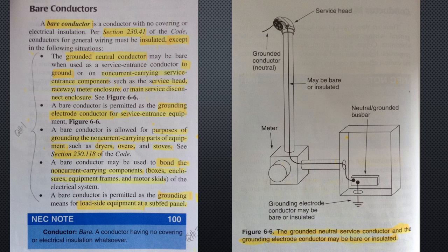Code requirements for conductors. In the code, Article 310, Conductors for General Wiring, addresses the general requirements for conductors: conductor designations, temperature considerations, environmental conditions, size limitations, ampacity, installation methods, material usage, insulation, and other factors concerning conductors. Refer to Article 310 when planning any residential, commercial, or industrial wiring installation.